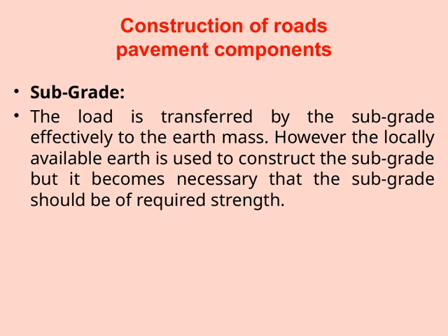If the natural earth isn't strong enough, we need to improve it or add materials to ensure it can handle the stresses. This step is crucial because the stability of the entire pavement depends on the quality of the subgrade. When constructing the pavement components, understanding and properly preparing the subgrade lays the foundation for durable and long-lasting roads.